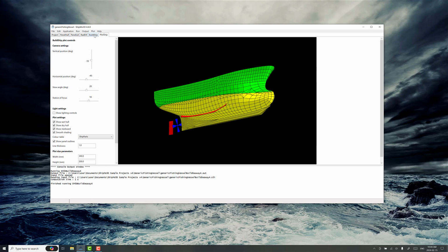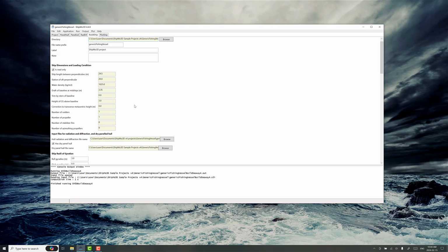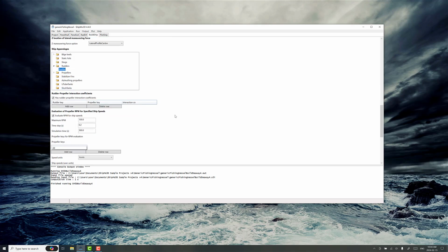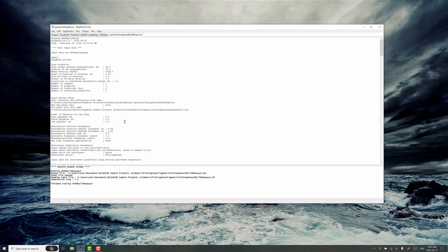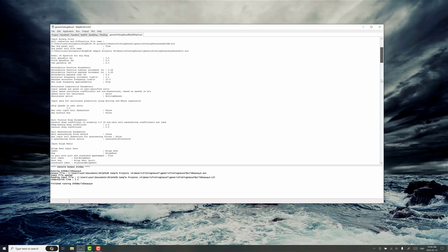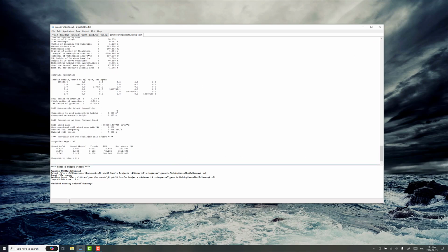Where we start off is you've got to have everything set up all the way up to build ship, setting up the ship model. One handy note: if you click on View Output after running this, way at the bottom of the file you'll see some interesting information on the natural roll period of the ship in that configuration at 0 speed. It's handy to know there's a natural roll period at 7 seconds, and we're going to pick some sea state conditions around that to check out some interesting ship motion.